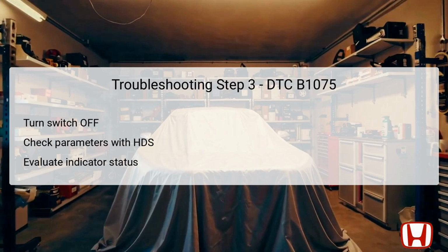If the indicator confirms that it is off, you can move to the next step of the troubleshooting process. If the information indicator is still on, it could indicate a latching fault or a wiring issue, prompting you to skip ahead to a more advanced check. Ensuring these statuses are evaluated is a critical component of isolating the electrical fault within the headlight system.